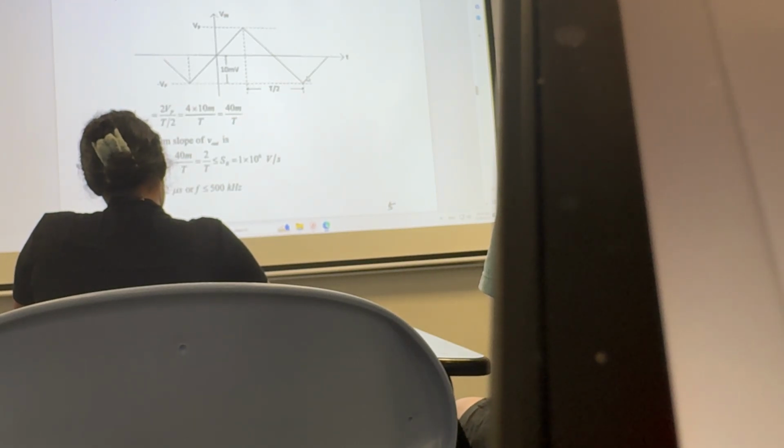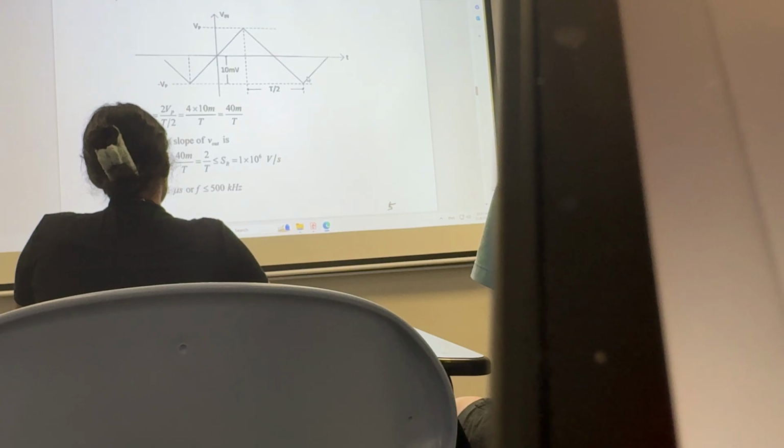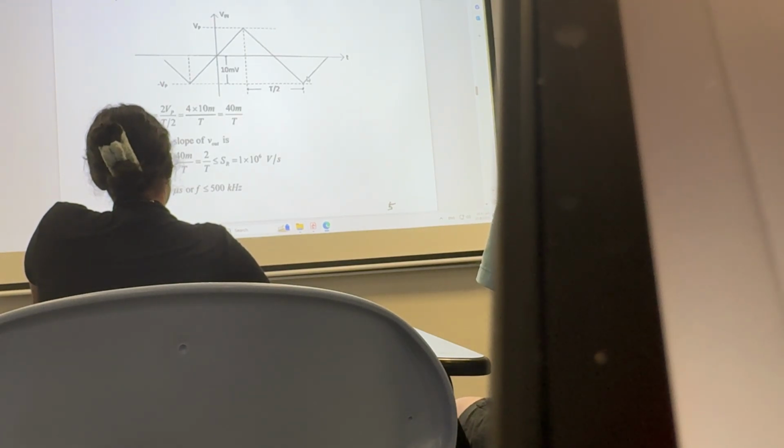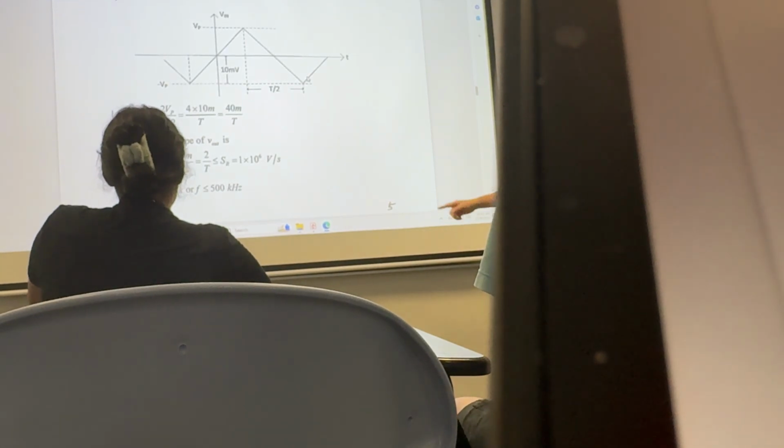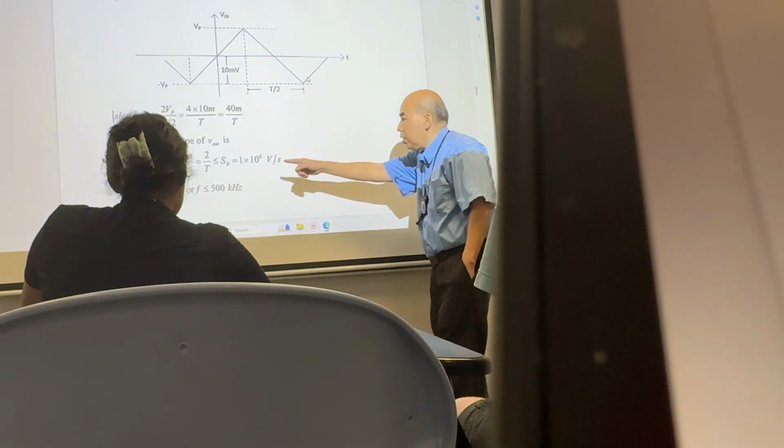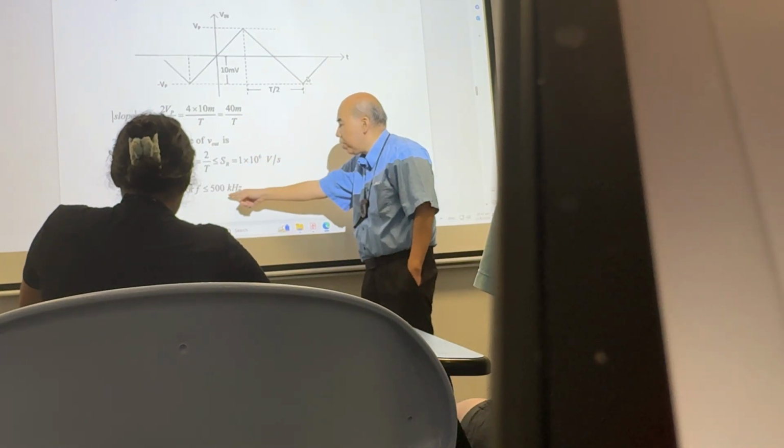So this is an input slope, right? This is an input slope. Triangle rate is an input slope. You see what we want? Slew rate is a rate of change of output with time, right? We need to know the output slope, right? Not the input slope. So you multiply the gain factor, and equate to the slew rate, you'll find that 500K.